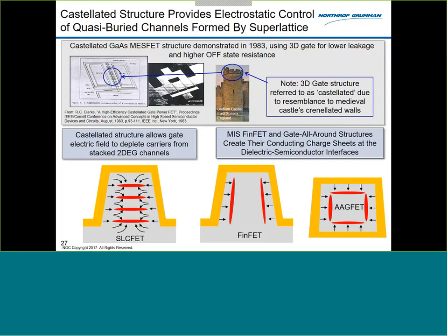So if you forward bias this device, you actually create an MOS carrier conduction path along those sidewalls. It doesn't dramatically change the on resistance. The on resistance gets a little bit better, not enough for us to do that as an ordinary thing. But from a power handling standpoint, you're putting more charge in it, so you can get more current, and you really do see that.